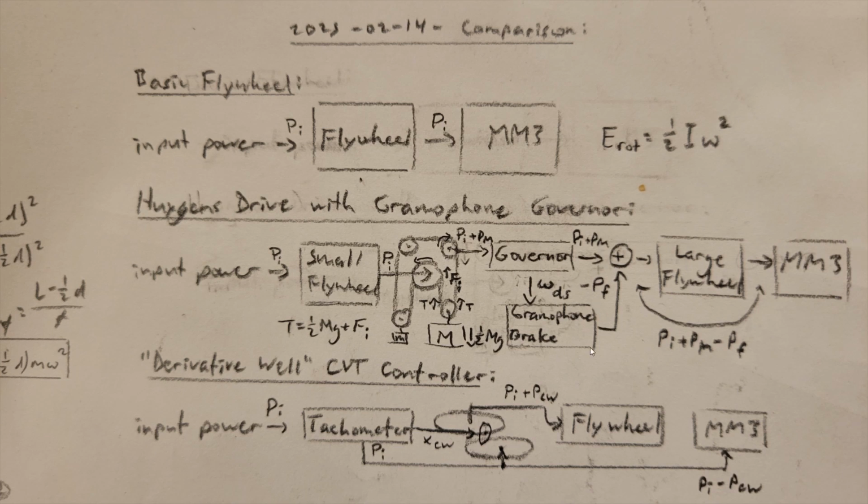As for why this design appears to work, it is because of the lack of a changing load and the efficacy of the visual feedback provided by the Huygens weight, not due to the design's resilience against changes in system energy. It would have probably worked just as well for a constant load if you were to have bypassed the Huygens Drive, removed the gramophone brake, and just adapted your input to keep the governor's sleeve at the same position.